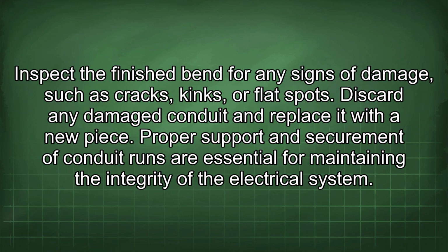Inspect the finished bend for any signs of damage, such as cracks, kinks, or flat spots. Discard any damaged conduit and replace it with a new piece. Proper support and securement of conduit runs are essential for maintaining the integrity of the electrical system.